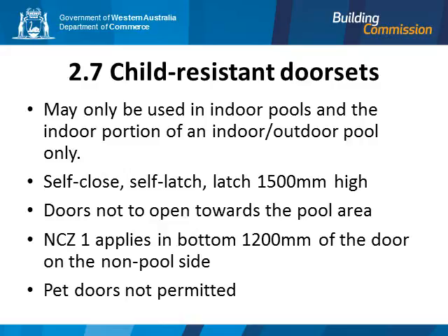Doors are only permitted to be used for indoor pools or for the indoor portion of an indoor-outdoor pool. Doors must be self-closing and self-latching when released from any open position, from fully open to resting on the latch. Doors must have a latch release located at least 1.5 metres high. Doors are not permitted to open towards the pool area, but may open away or may slide sideways.